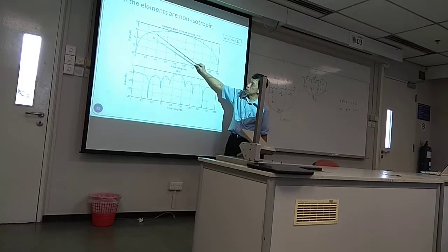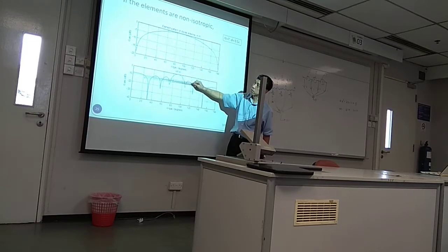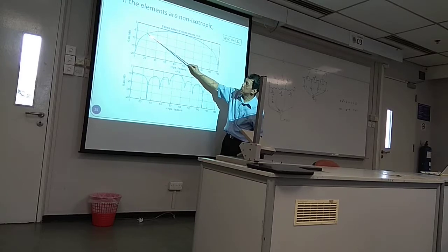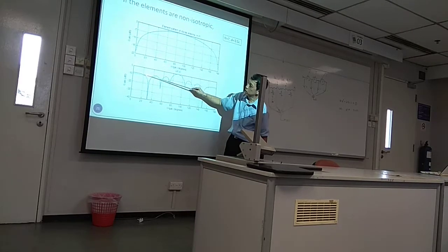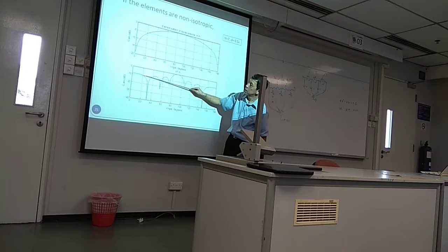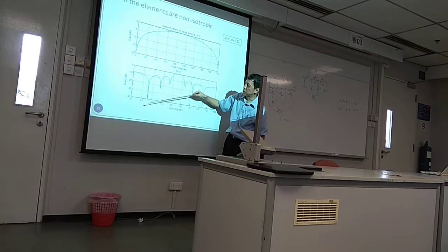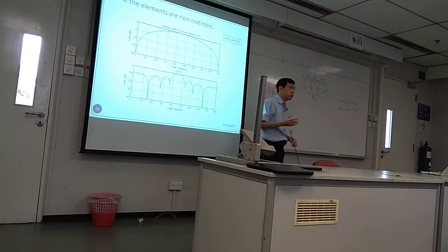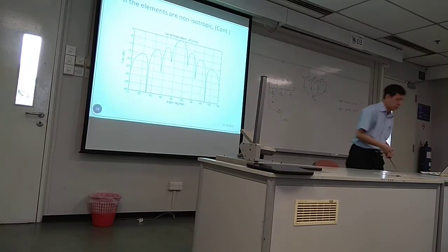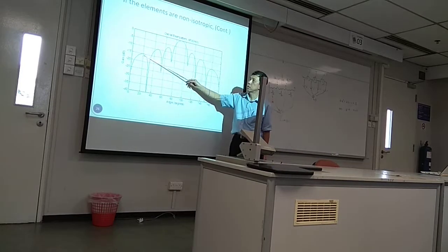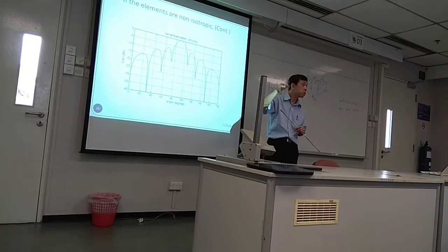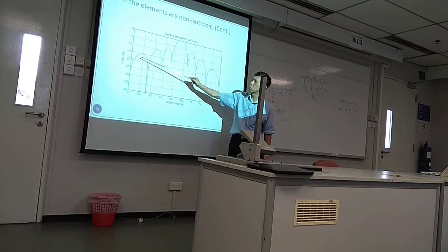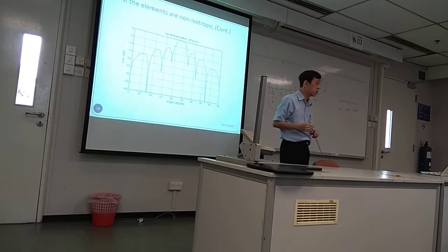If the two beam patterns are expressed or drawn in terms of gain in dB, then at this point, if you have a -6 dB, and over here we have about -10 dB, then the overall response at this angle, 20 degree, will be -6 plus -10, and that should give you about -16. Of course, my estimation wasn't accurate, so it is around -15 or -16.